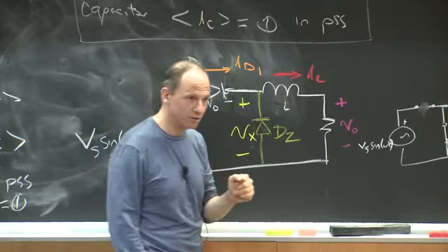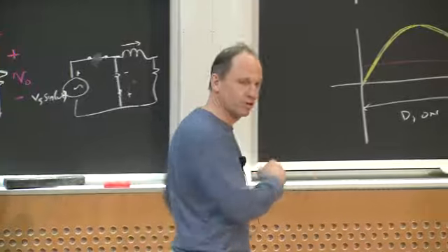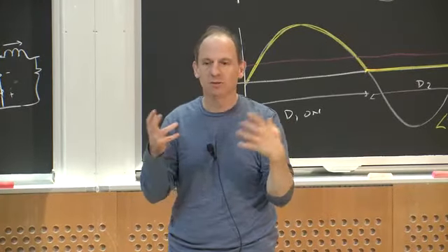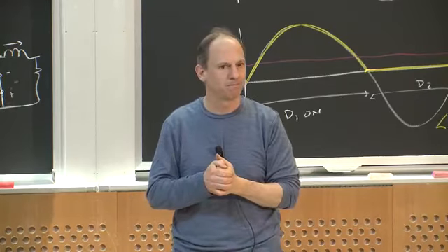So to conclude, what we've got is the method of assumed states to figure out when our diodes are turning on and off, and periodic steady state operation where we can use some of those relationships to start figuring out what voltages and currents I'll get in my circuit.